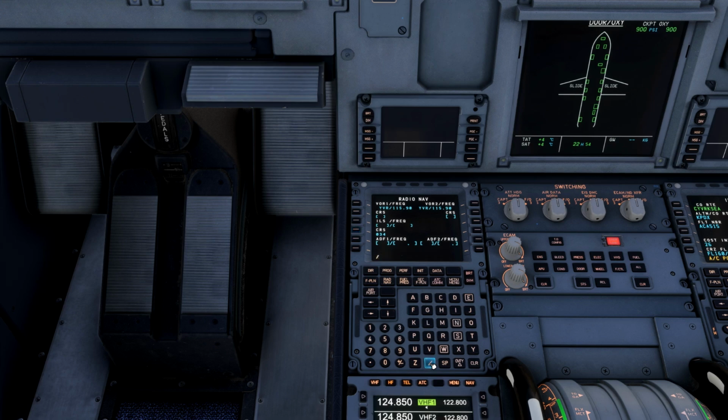And then we go to the navigation screen, radar navigation. We add our ILS frequency for runway 34 right, 110.3, and landing final direction course at 034, of course, to match the runway. Add our details. Departure is 08R. We're flying from Stanley 5. Insert that into the flight plan. And for our arrival at SeaTac, we are arriving 34 right. There it is. Auto procedure Mariner 8.